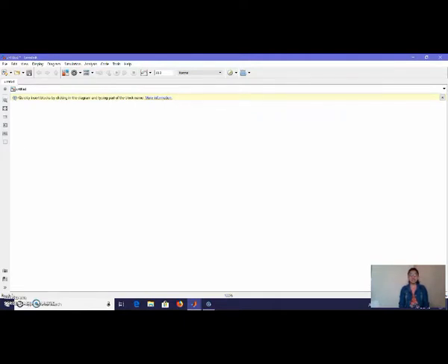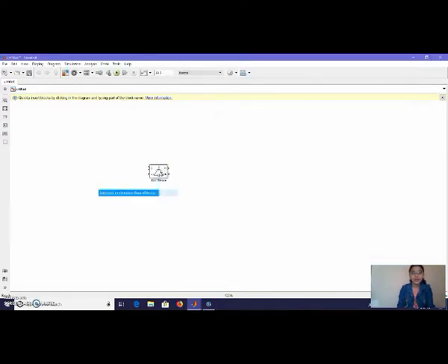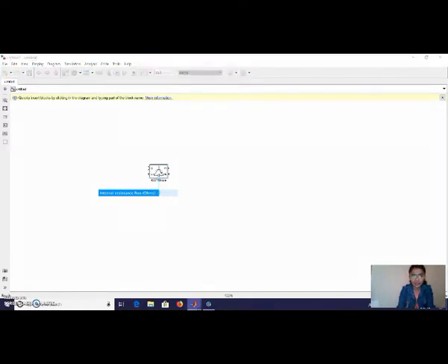Let's take IGBT. So open the library window by pressing Ctrl Shift L. Type the name of the component that you want. That is, now we want IGBT. So drag the IGBT and place it in the window. We will also need the RLC element.